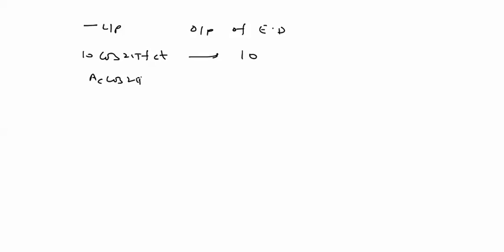When we apply input on it, the output of the envelope detector, because it is a peak detector circuit: for A cos 2 pi fct, the result will be A. If we apply e power minus t cos omega ct, the result will be e power minus t.